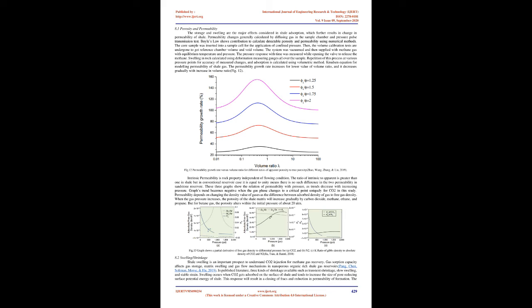When the temperature of the shale matrix increases, the adsorption of gases will decrease, so swelling of the matrix also reduces. When the pressure in the shale increases, the adsorption of gases in the matrix increases to cause deformation even as the temperature rises. There is a sudden increase in volume strain due to pressure increase, and it reaches a plateau at higher pressure. Moisture effect.